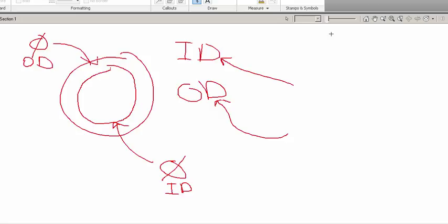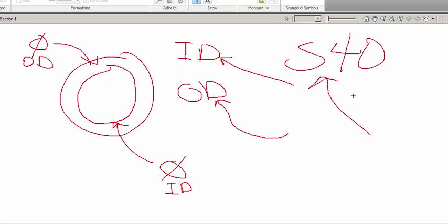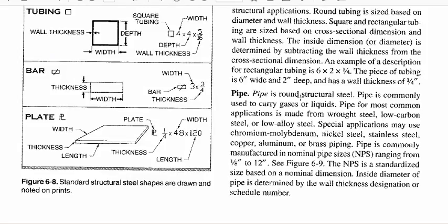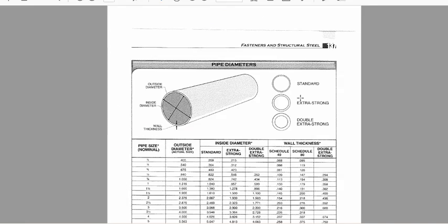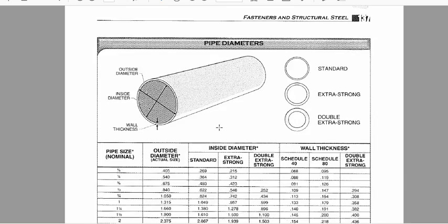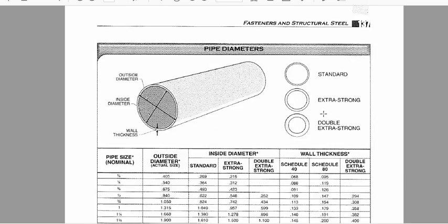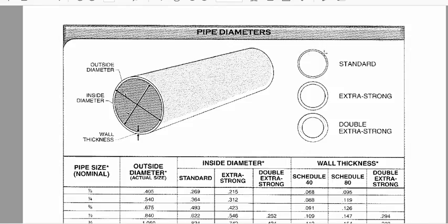Also, there are about 3 different grades of pipe in terms of standard, which we refer to as Schedule 40 pipe. And then we've got larger versions than that, but this is your standard. If you just go in and order a pipe, that's probably what you're going to get. It's your standard wall thickness, and then they increase. To explain it better, let's take a look at a chart, which should always be your go-to move anyway, checking out charts and graphs, or the internet. So for standard, here's your typical wall thickness.